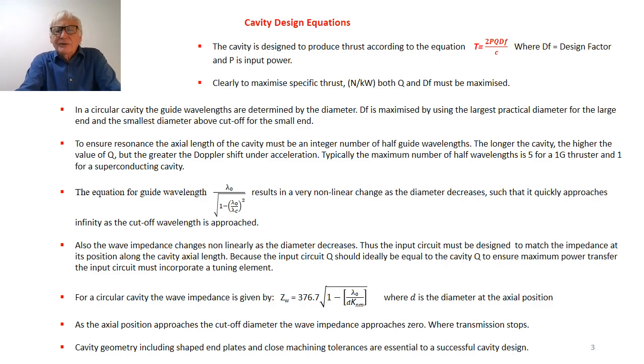The basic thrust equation is shown there, and you can see that T is dependent on power, Q, and something we refer to as the design factor. Now, to maximize the specific thrust in newtons over kilowatts, the Q and the design factor should be maximized.